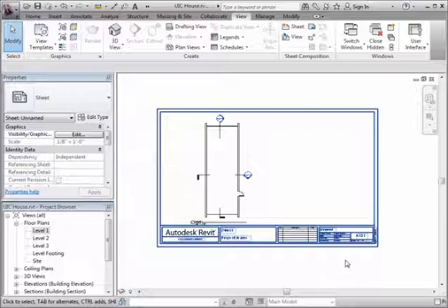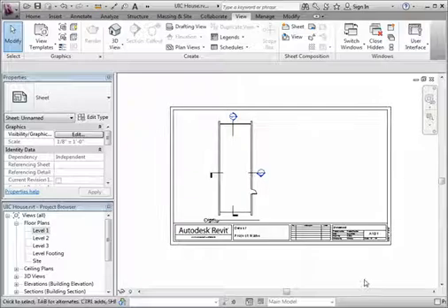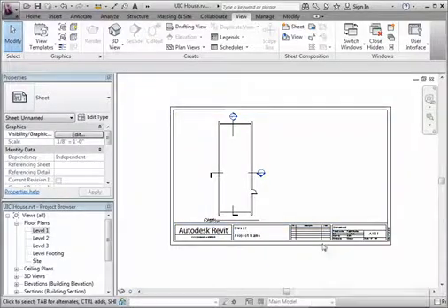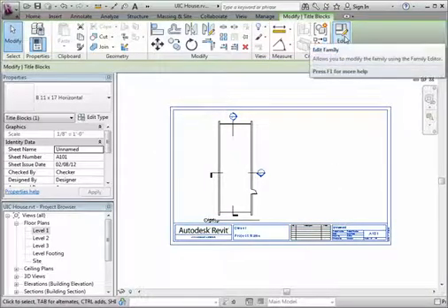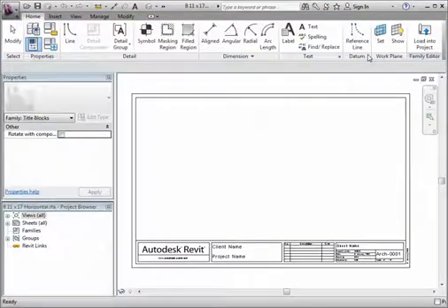And then real quick, this title block is mildly annoying, so I want to change it. A title block is a type of family. So this will show you a little bit of the process of how you customize families. So I'm going to select this title block. And then up here it says Edit Family. And what it does is it's sort of unusual. It actually opens it in what's called the Family Editor, which is a little bit of a different working space.